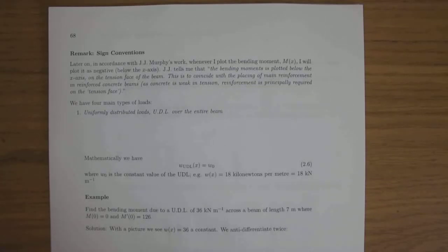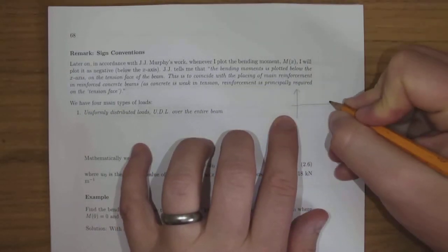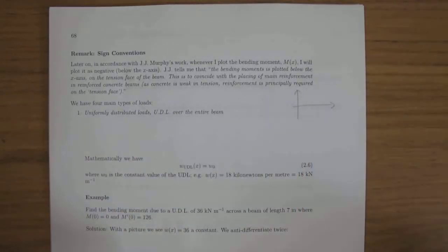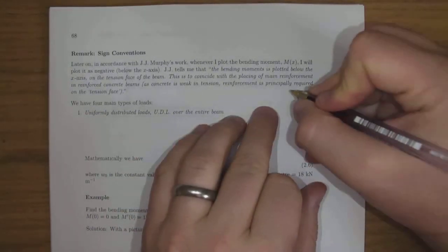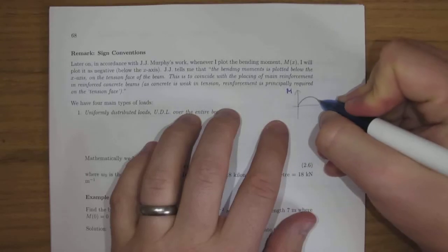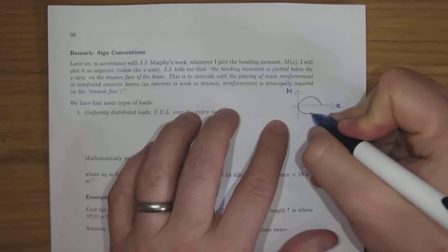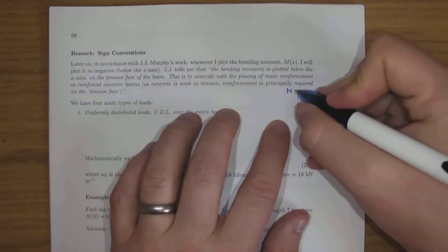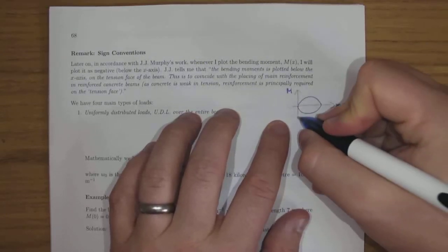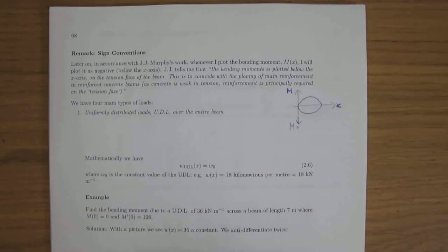Okay. So I'm just going to show you what I mean there. Say the bending moment went from 0 to a maximum and back to 0. With the maximum being positive, mathematically you'd graph it like that. But in engineering, you graph it the other way around. So actually, rather than this being positive for the bending moment, the positive bending moment is down. Okay, so we're going to talk next about the different loads that we have.